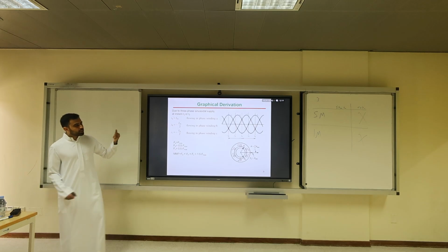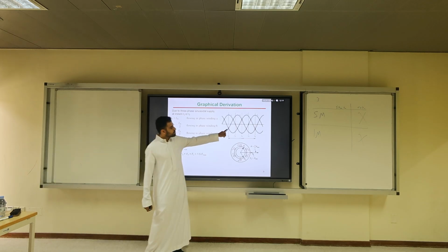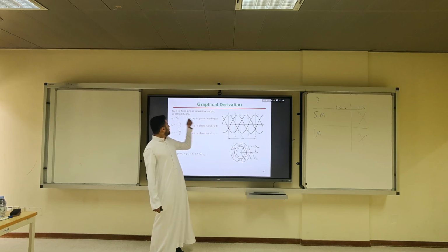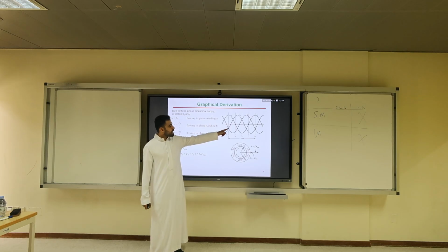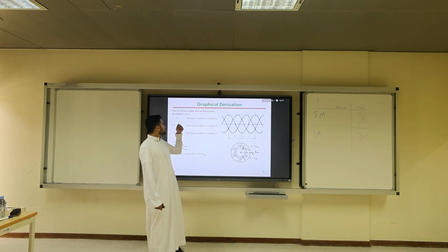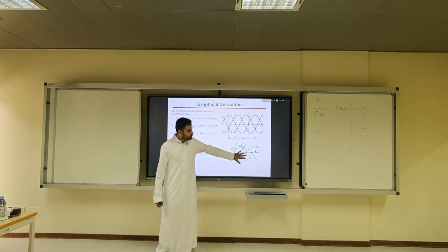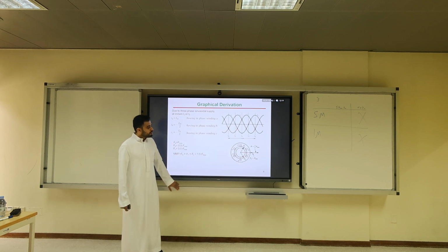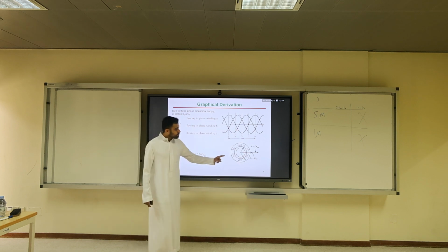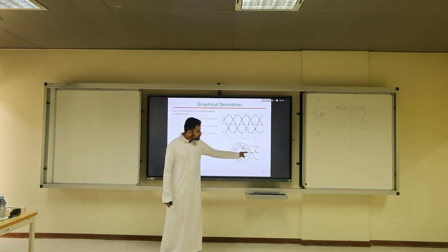The other thing is, look at, for example, time zero here. What is IA? It is I max. What is IB and IC? They are negative I max over 2. If you convert the current to MMF, note that IA is here.